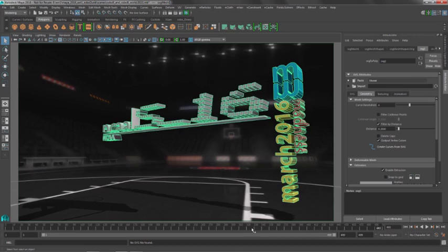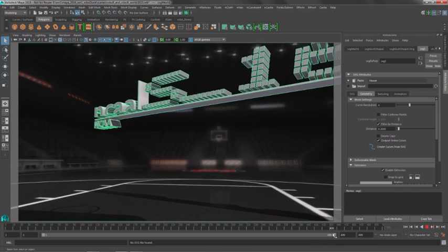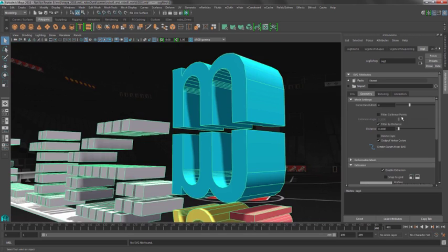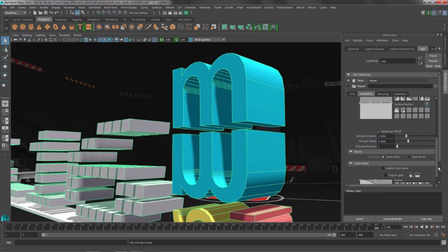So you can see Maya goes through, and it really quickly builds us this nice extruded piece of 3D geometry from that vector information. Also notice that Maya generated shaders for us based on the colors that were in that original Illustrator file. Now we want to further refine this, so we'll jump over to our perspective view, and you'll see that we have a curve resolution. This is going to define how many polygons are being used to try to capture that vector information. So it's resolution independent.